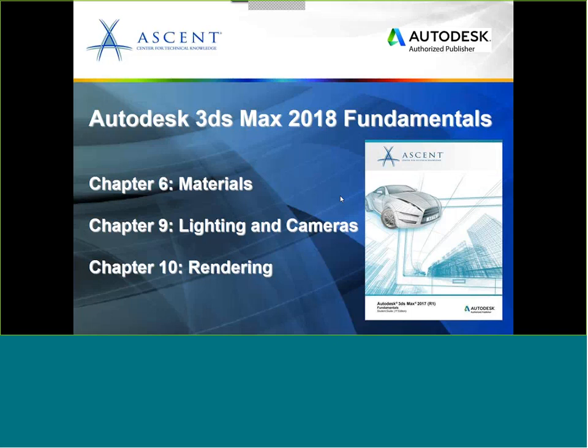And finally, I'll be taking the information from Chapter 10 of the training guide and give you an overview of the options that are provided to set up the Arnold renderer. Just to add, this newly incorporated renderer replaces the NVIDIA Mental Ray renderer. Although 3ds Max is still compatible with the Mental Ray renderer, it does not come in as a built-in renderer any longer.